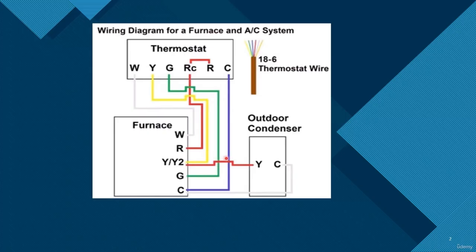Now these little jumpers here, what that does is indicate that there's no physical connection. Same thing up here. It just means that the green wire is not connected to the red wire in any way. It's just going across it. Now if you saw a dot kind of right there, then that would indicate a connection. But if you don't see a dot, then you'll have these jumpers that tell you that it's not connected.